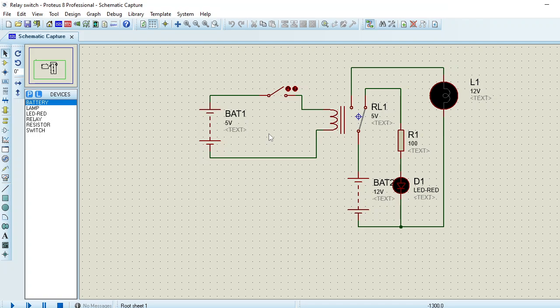Alright, in setting up the relay, it has 2 basic configurations, which I've shown you in the picture below: the normally open, which is what I'm touching now, and the normally closed. In the normally open, where my cursor is, the circuit is open and there is no current flow to the load. When I say the circuit is open, it simply means the circuit is broken, or off.